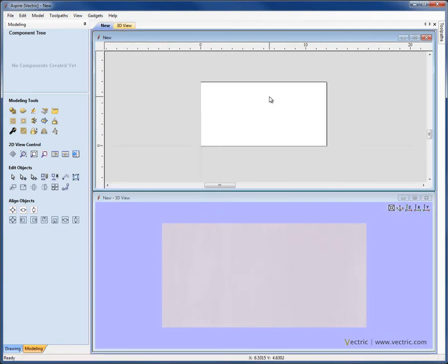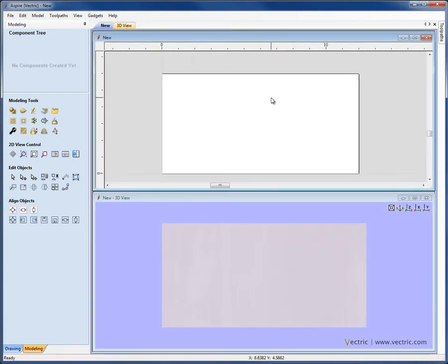The next type of file that I want to show you being imported is a mesh file. Typically, file format you may find for something like a mesh is going to be STL or a 3D DXF. But it has to be a mesh. It cannot be a wireframe file. It needs to have some sort of a skin to it to be able to import it into Aspire.